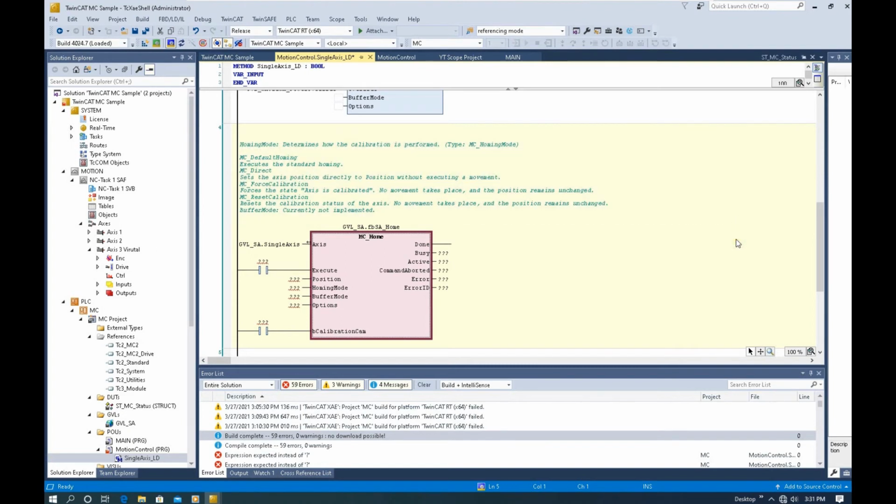So that means we can use the jog mode, line up the tool first, and then execute this command. And at that time, it will directly write one value into our axis. This is the tooling lineup. Then we will connect the variables here. This is the home execute, and this is the home sensor.